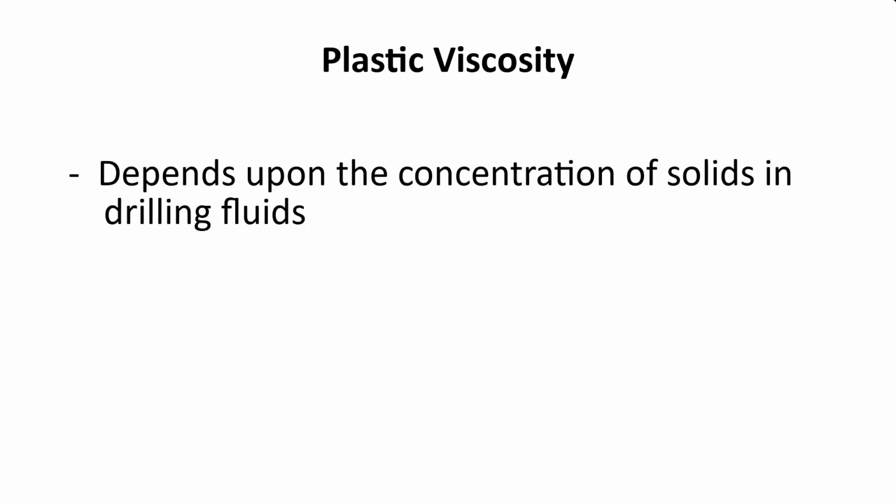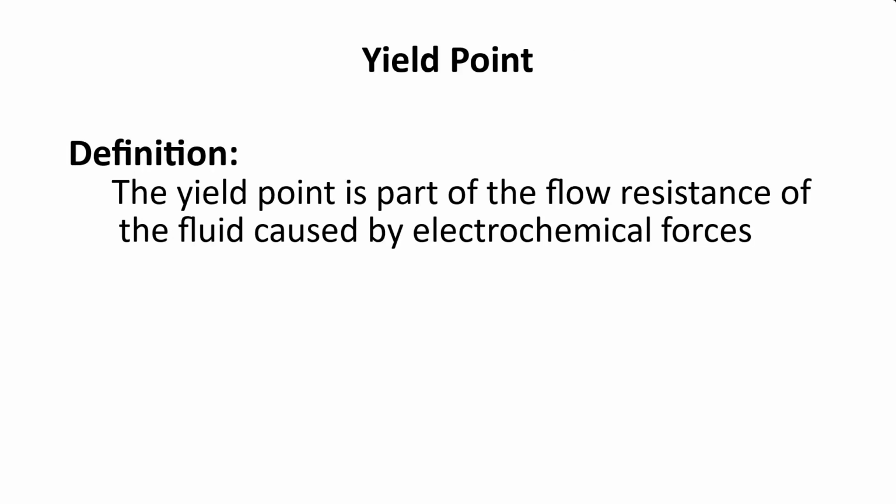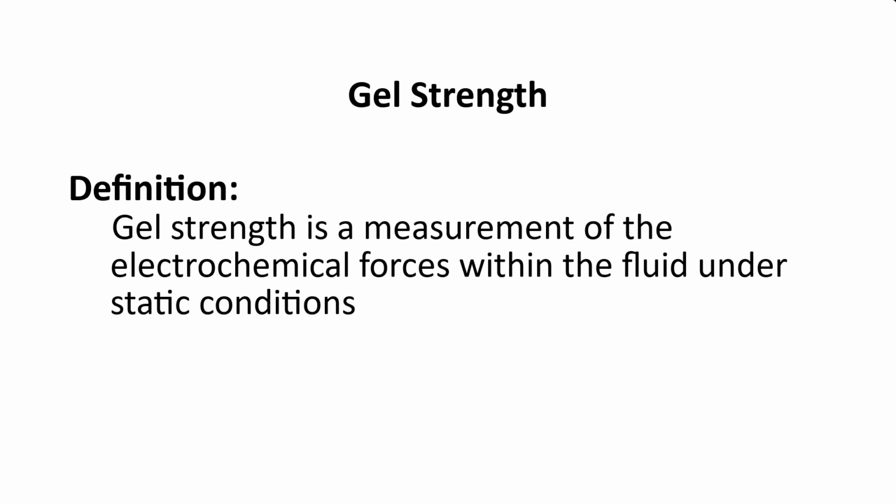For practical purposes, plastic viscosity depends upon the concentration of solids in drilling fluids. Plastic viscosity is also a function of the viscosity of the fluid phase. The yield point or yield stress is part of the flow resistance of the fluid caused by electrochemical forces within the fluid. The forces are due to the charges on the surface of the reactive clays and submicron particles in the presence of electrolytes. Gel strength is a measurement of the electrochemical forces within the fluid under static conditions.